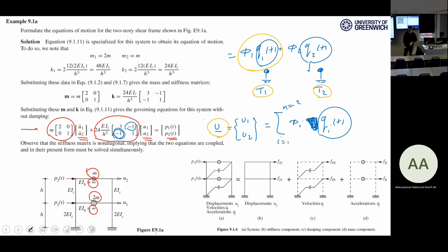But civil engineers usually feel like working with T. Most likely, mechanical engineers like to work with hertz, with frequency. But when I say natural frequency, I really mean T1, T2, T3. I mean natural period. They are all the same thing, but in different forms of presentation.